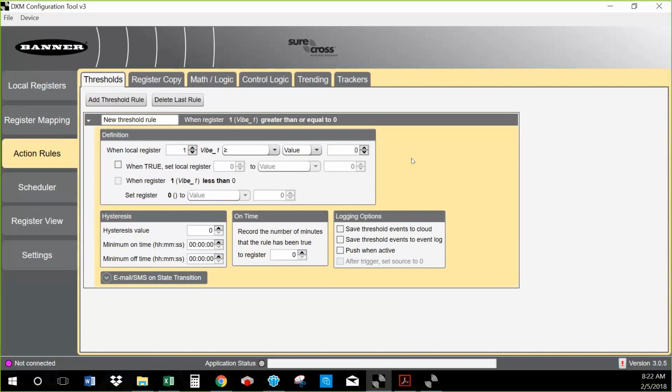So generally what you would want to do is have this sensor running on your motor so you know about where its base vibration is. So everything you know about where it should be running when everything's good, and you could put a number here. Now I'm just going to put in 1500, which would be a very low number. Just so you know, this would be the same as 0.15 inches per second vibration, which would be a pretty low vibration. The motor would be running pretty well.